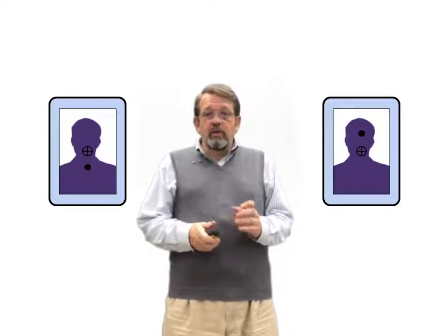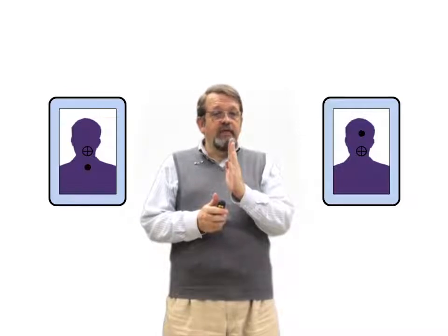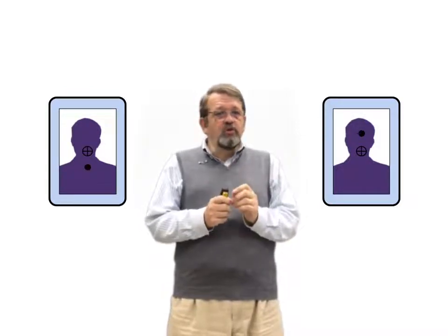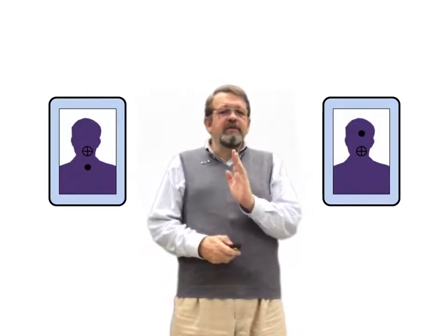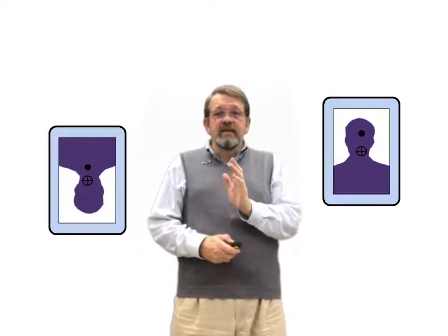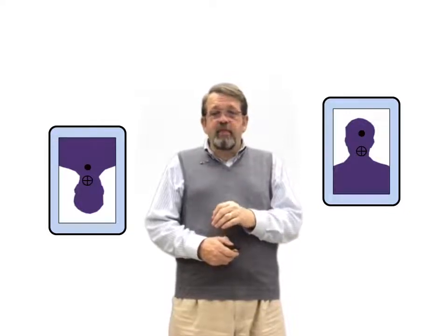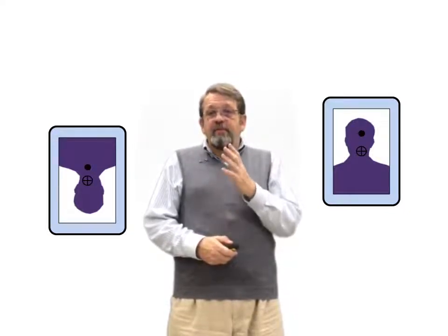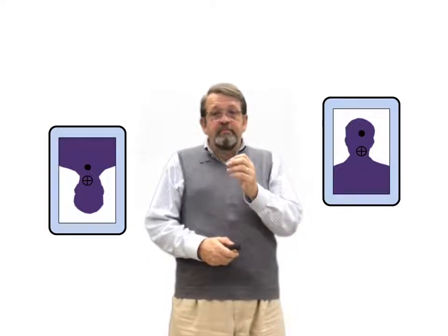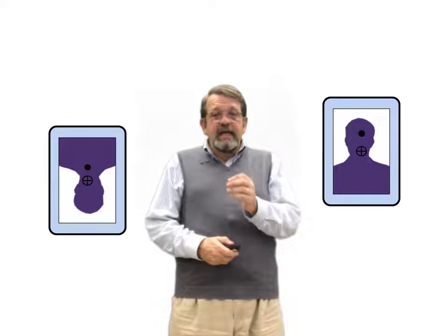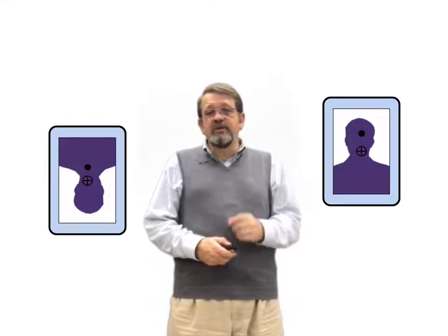So let's imagine that we're putting the nail along that center line so that we can hang the picture up without it tilting. Suppose we put the nail below the center of mass. Then if the picture were exactly upright, everything would be fine. The nail would be supporting the picture. But if the picture were tilted at all, even a fraction of a degree, then what would happen is the picture would completely turn upside down. Or it might even fall off the wall. The point is that the picture is unstable if the nail is below the center of mass.